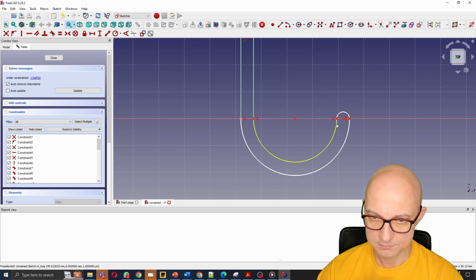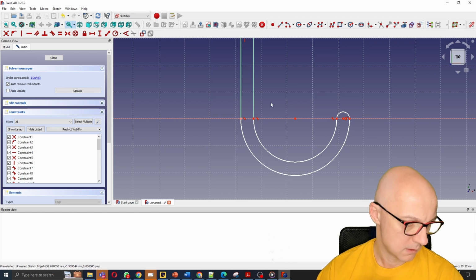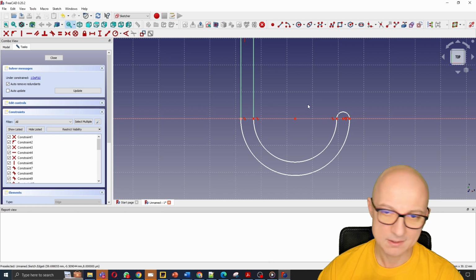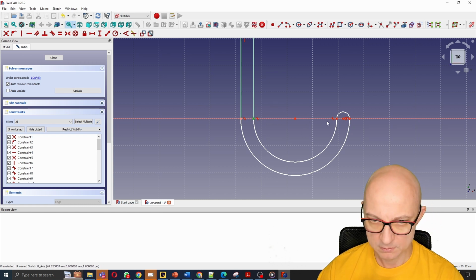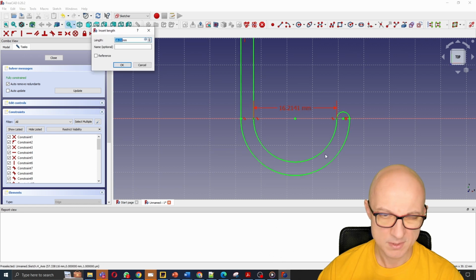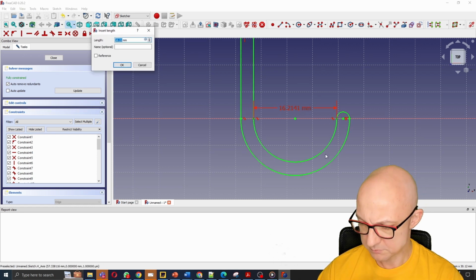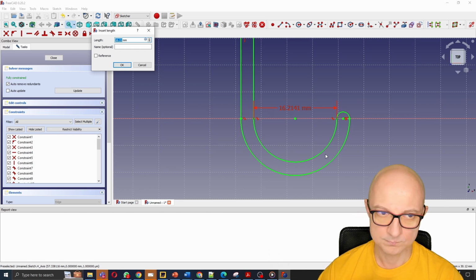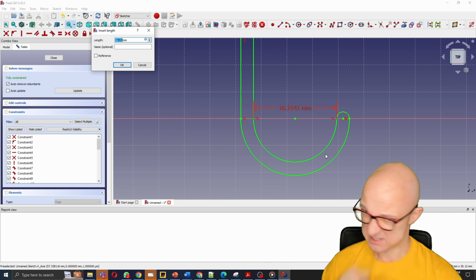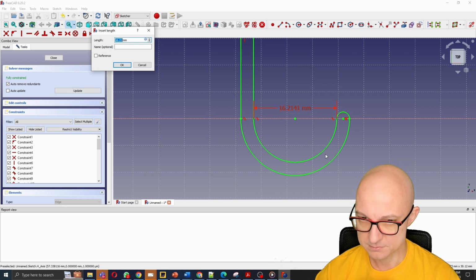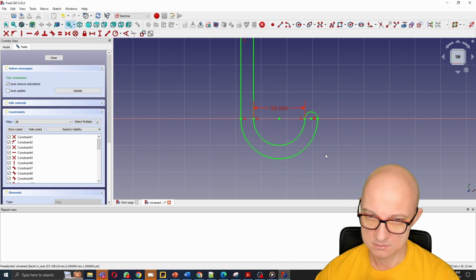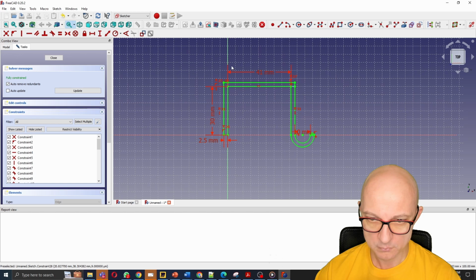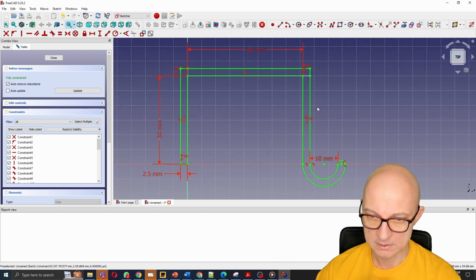And if you consider that part of our hanger will go here, we may want to define this size. And if I imagine a hanger, it usually will be probably 5 millimeters in size. So let's assume we'll make it, let's say 10. Let's see how it looks. 10 mils. Okay, and now it looks like it is fully constrained, it says fully constrained, it's green.